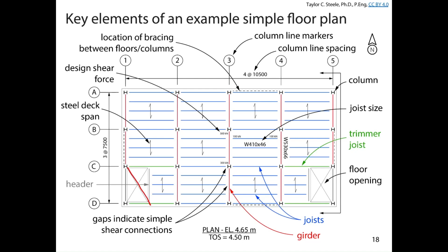If you need to make an opening here, for example, if you want to throw a big elevator shaft up through this space, you need to frame a floor opening around that. And you do that by spanning a header to the other joists and then using short joists in between the header and the opposing girder.